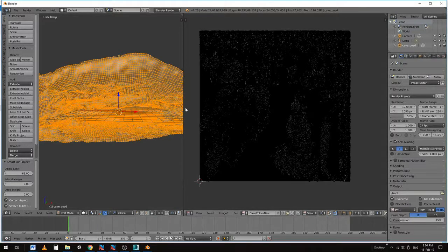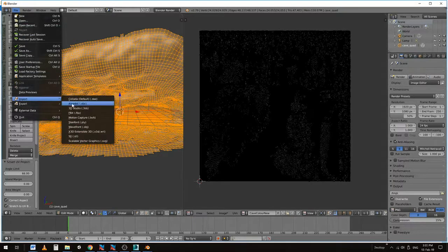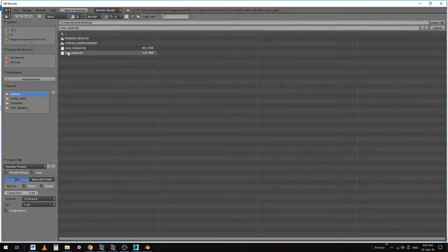And so what we need to do is we need to take the texture information from the original model that we saw in 3D Studio Max. We need to take that and we need to somehow put it onto this system. So Blender gives you a really wonderful way of doing that. And so what we're going to do now is we're going to import the original complex model into Blender. So I click Import OBJ, and I go to the Cave Original file, and I click it.